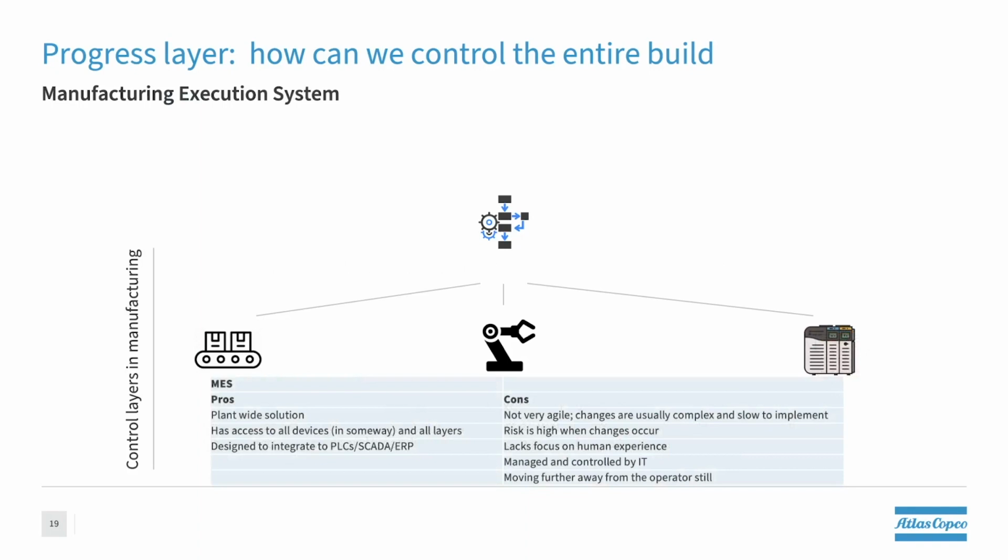It's designed to integrate with existing devices within manufacturing environments like PLCs, SCADA systems, and ERP systems, which allows them to enhance already running plants. The cons are the MES is not very agile, and changes within MES are usually complex and very slow to implement. When changes do occur, the risk is very high. The MES usually doesn't focus on the human experience, and the MES is controlled and managed by IT departments, who themselves are quite removed from the needs of manufacturing.